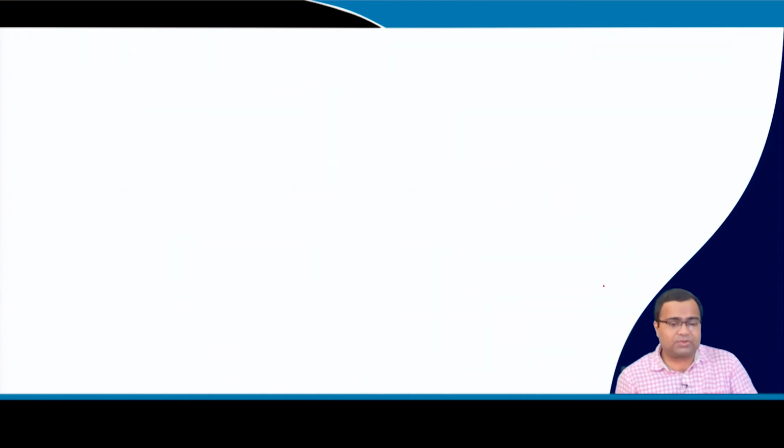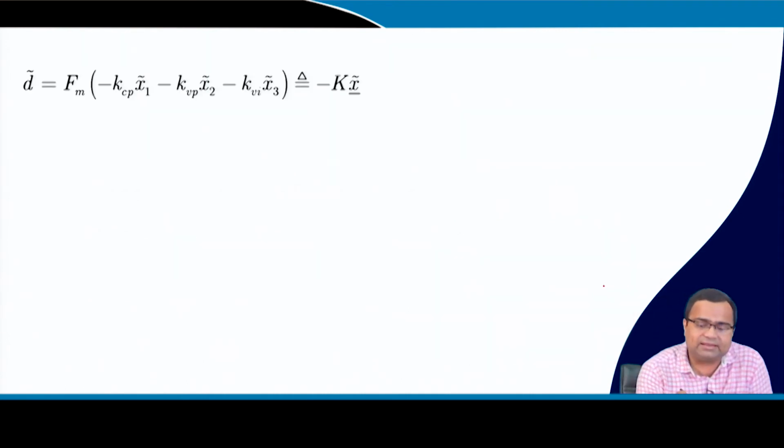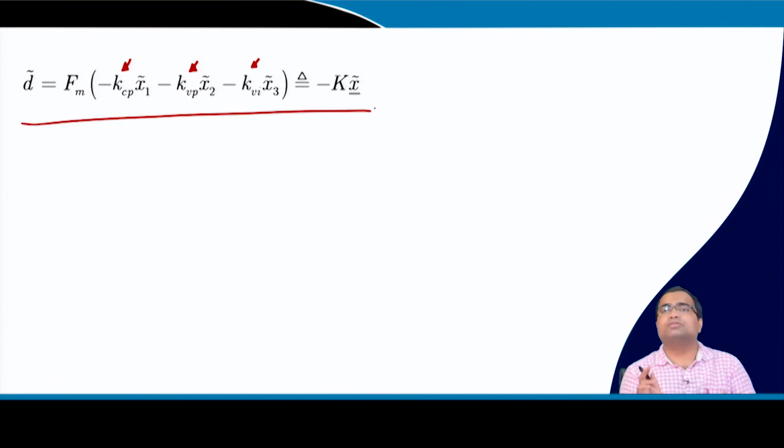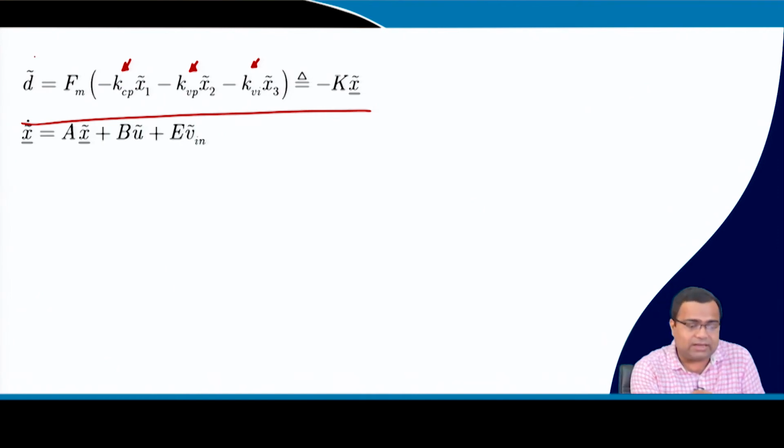Okay. So, we can take these gains, the voltage controller integral gain, voltage controller proportional gain, and the current controller proportional gain that we have discussed, and frame them into the feedback control, where the duty ratio is generated by their combination. And what is the modulator gain?